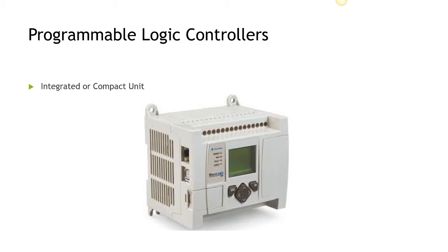This is a MicroLogix 1100. It's an offering from Allen Bradley. And it is called an integrated PLC because it is not only a central processing unit of this PLC, but it also offers some inputs and some outputs natively on it. So that's where the term integrated comes from. We don't have to buy extra components and add it on here to be able to wire physical field devices to it or physical final control elements from it.